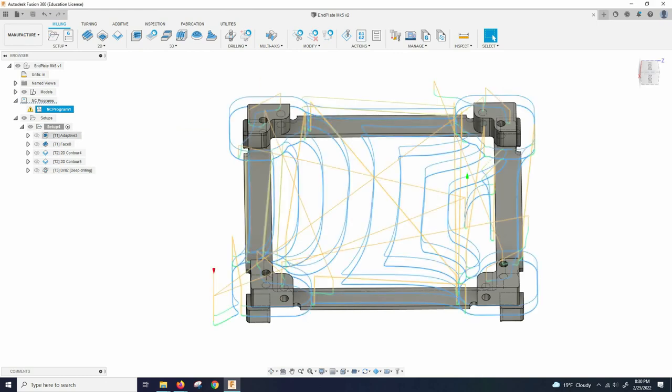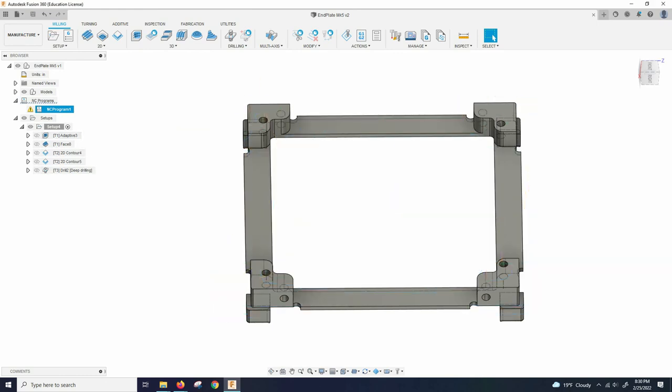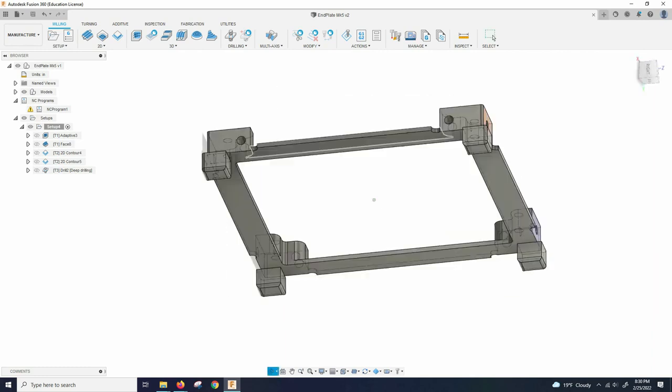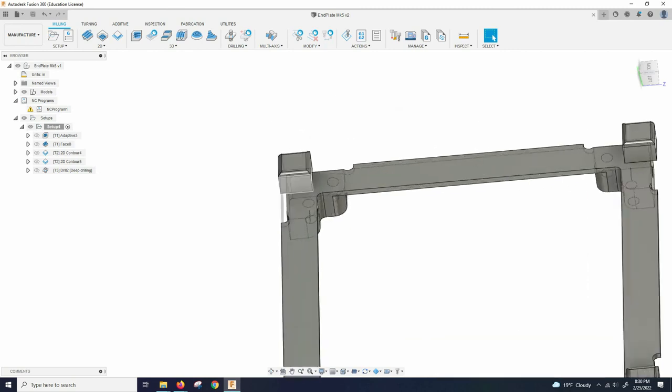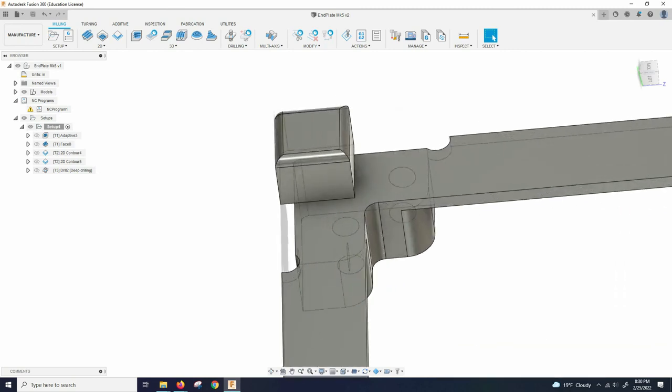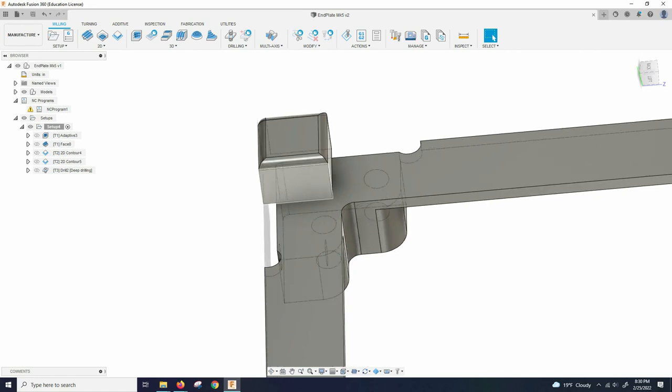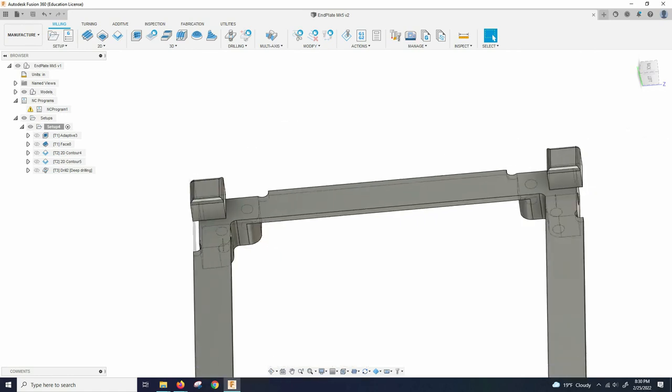It's really important to know tool 1, tool 2, and tool 3 because when you put it into the machine, these tools need to be in those spots on the machine. Our machines can only hold up to 8 tools, so try not to do things too crazy. Like this, we did all of this with just 3 different tools. For this side, you can probably use all the same tools. You'll still do the face, the adaptive clearing, and the contour. You'll have to add one tool, and I highly suggest adding it as tool 4 so you can just load them all in. You'll need a radius tool.